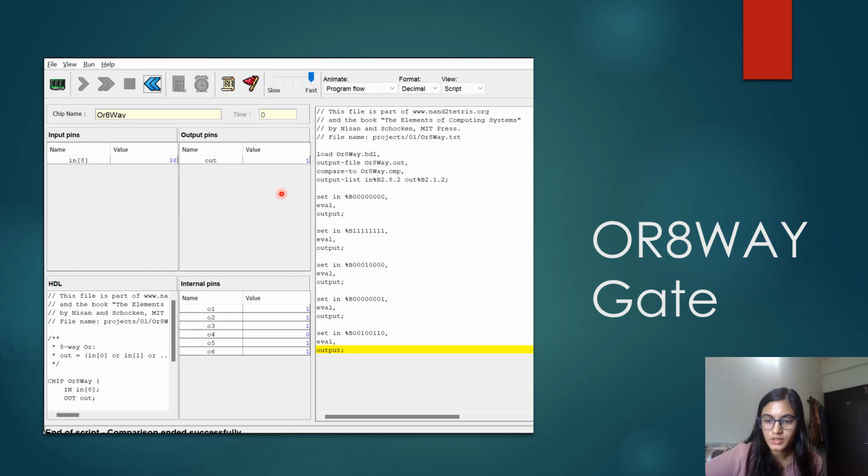From these 8 inputs we get 4 outputs. Then we perform the OR operation again on these 4 outputs, one for the first and second, one for the third and fourth. This gives us two more outputs. Then we perform our final OR operation, and this will be given as the output. Here all the 8 inputs are of 1 bit.